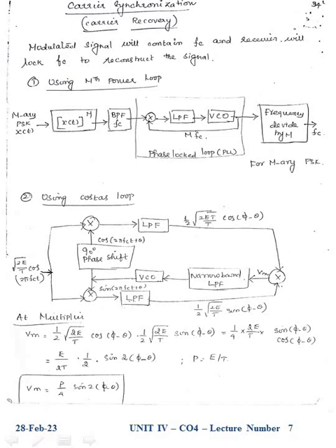As we discussed, synchronization is nothing but we have to synchronize the carrier frequency which was used in the transmitter. It has to be used in the receiver section also. The same carrier frequency has to be applied in the receiver section. That is coherent synchronization.